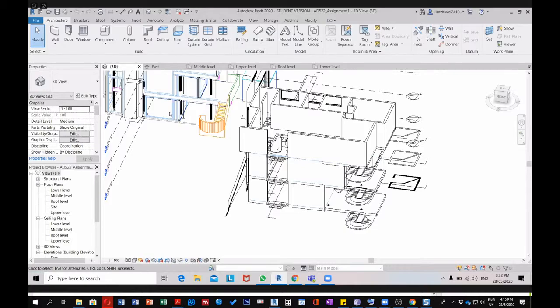So for example, let's say I did this wall. I have a wall already here, even though I changed the thickness, so I will bring the thickness again as it was before. So windows is very easy. From the Architecture tab, I go to Window, and then I select the window type which has the same dimensions as the 3D.